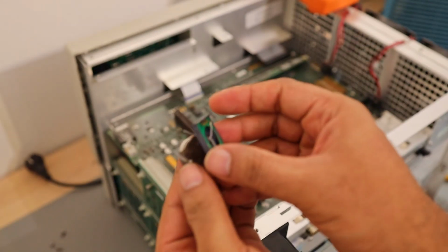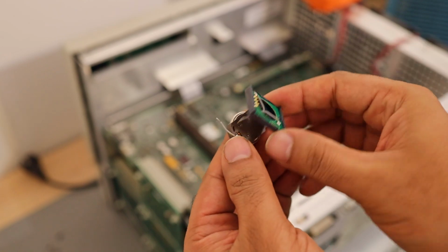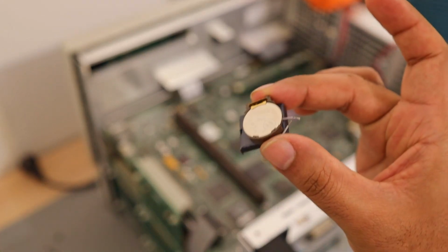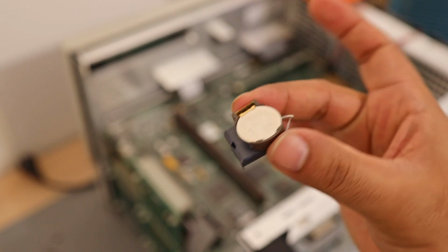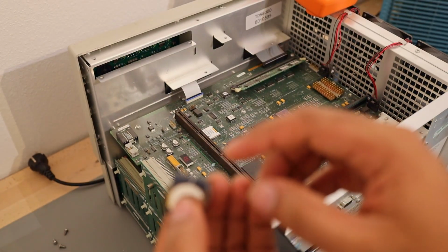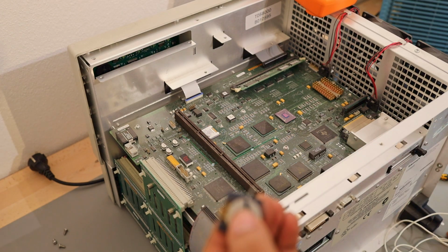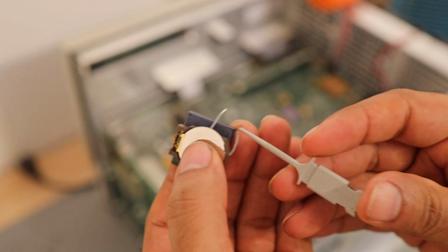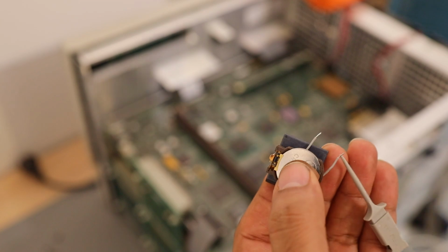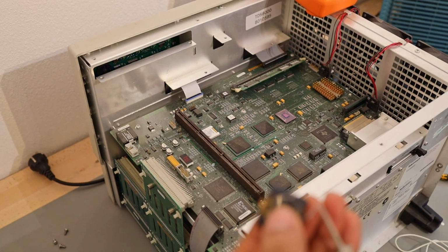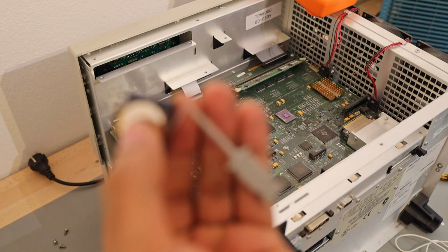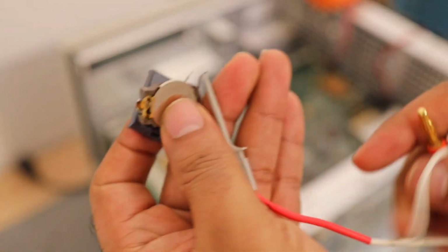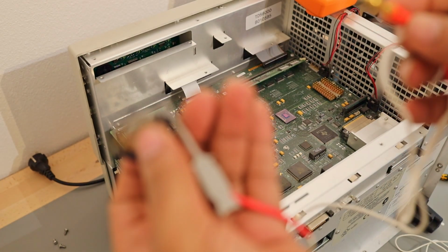See, I did not have the appropriate cell, so I just didn't replace it. I made this little thing. I'll glue this here with a CR2032 on top. This will give you the possibility of measuring the current. I intentionally left 2 pins open. We will use hooks like this to connect, and I have these kinds of probes or leads. They will hook into this like this, and then I'll be able to connect my multimeter to it.